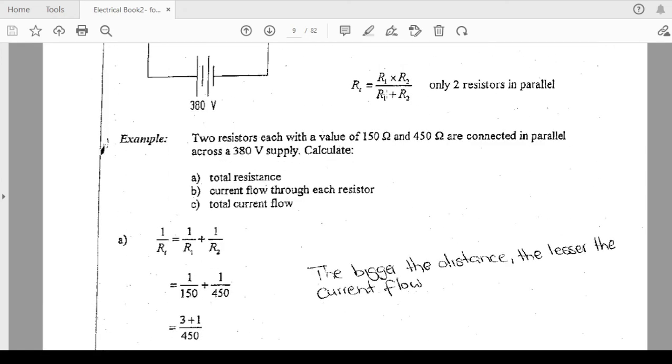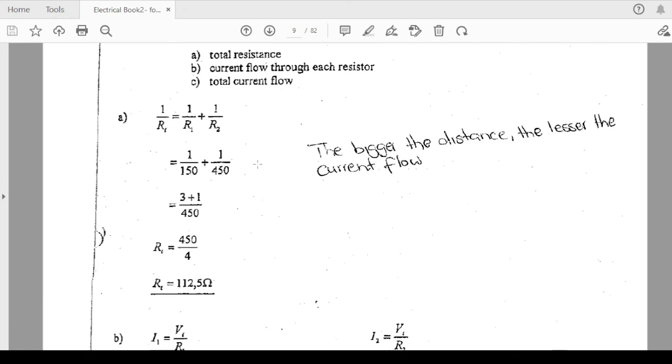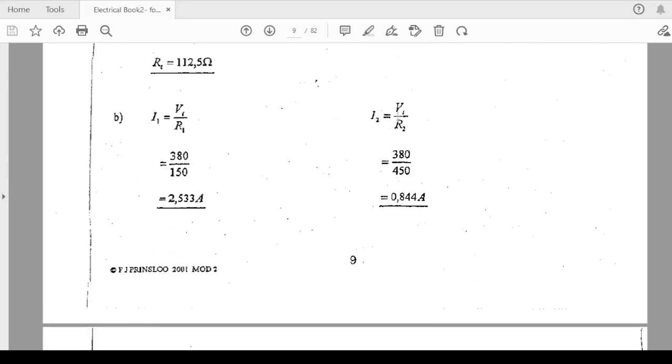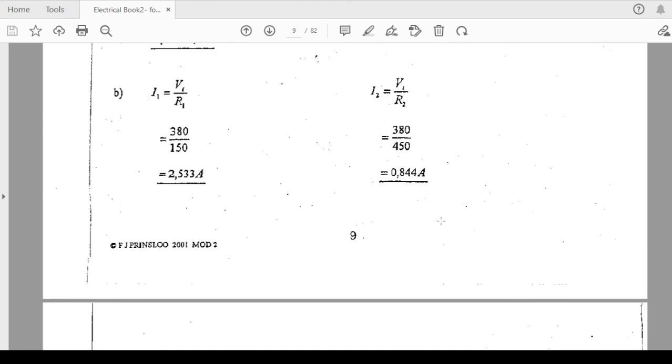You are going to work with that resistor, 100, and the voltage it's losing, you put on top. When you divide the two, you are going to get the current in that resistor. But because it's series resistance, you know that the current is the same at any point. The same current for R2 is the total current, is the current at R1, is the current at R3. So we work with resistor 2 to give us how much current it's taking. But in series, current is constant, so whatever answer you get is the same everywhere.